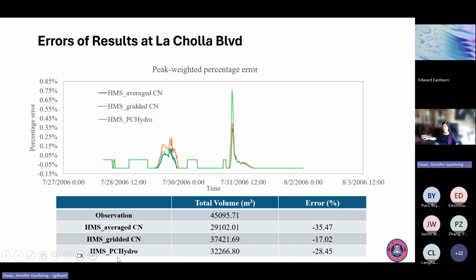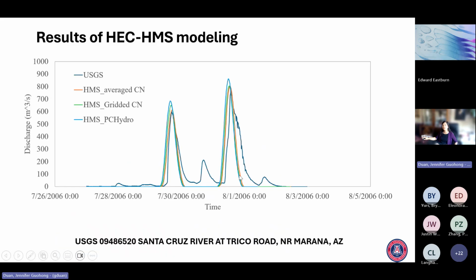And we're going to continue, and this one showing the new graded curve number getting a little better result, but that doesn't mean it is better. All right. And continue, we look at the Santa Cruz River, and at the Santa Cruz River, the prediction looks at the three different approaches and the USGS record. And apparently we see the green and the orange over predicting.